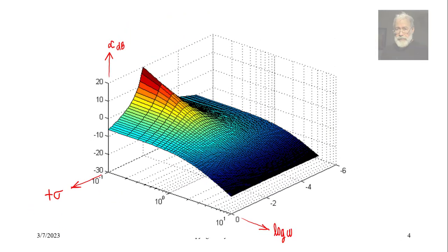Look, in this plot, we visualize the decibels contribution of that transfer function at any complex frequency on the complex plane. s is equal to sigma plus j omega. In particular, the intersection of that surface with our paper, represented with those light green lines, is the amplitude Bode plot that we're looking for.